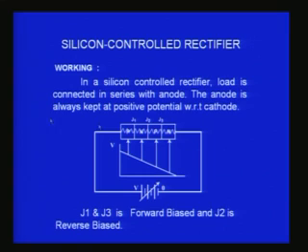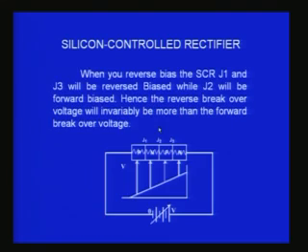So, when I look at it in that perspective, the p type is earlier than this n type, and therefore this should be more positive than the n type, and therefore this junction, with the p type more positive than the n type, should be forward biased. You all know that. Now, if you come to J2, the n type is more positive compared to the p type, and therefore it will be reverse biased. And J3, where again the p type is coming before the n type, and it is at a slightly more positive voltage than this, and therefore this also will be forward biased. So, you find J1 and J3 are forward biased and J2 is reverse biased. That is the situation corresponding to this.